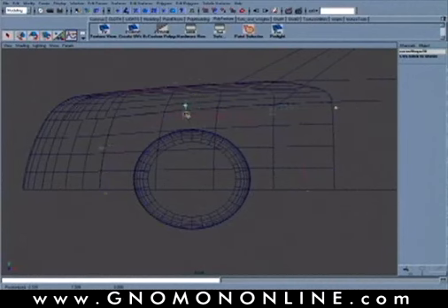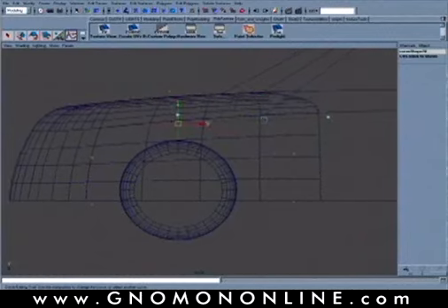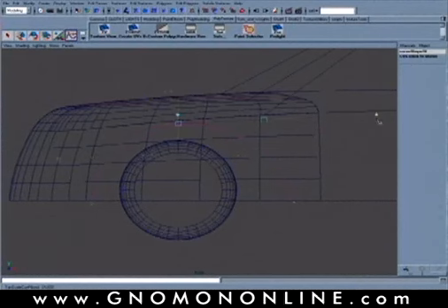Notice that when I'm doing this, though, it is affecting the other points that I already made tangents. So you may want to get this one locked in first. You can also play around with the scale of this by grabbing the diamond at the end of that translator and drag this as kind of a scaling tool. All depending on the number of points you have as far as how many control points you're going to want on that curve. If you don't want this part to be moving too much, you may want to have more points in the middle of that arch.